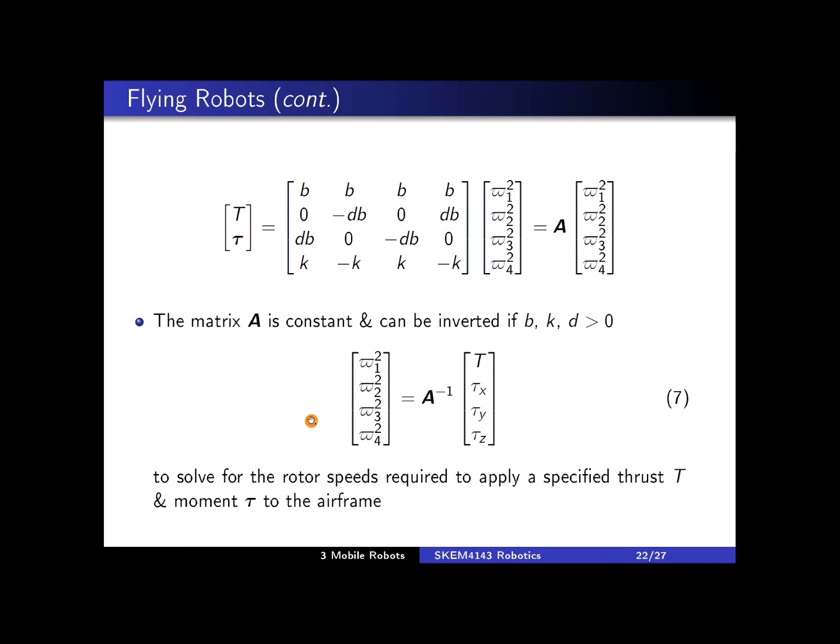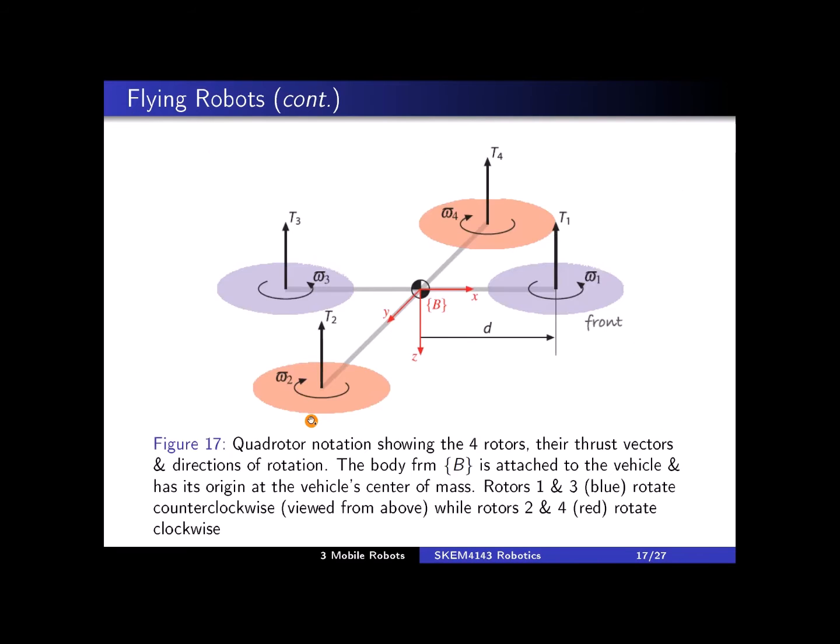Because you know that if we look at our quadrotor, the main control input is simply the angular speed, right? The way our propeller rotates, or the angular speed, how fast it is, will produce the required torque and thrust. But of course, how do we generate that angular speed? You need to provide torque, right?